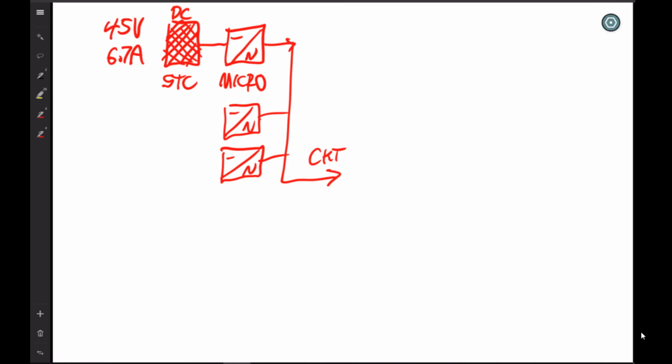I believe I have 13 modules on my roof, and I use microinverters at my house. I didn't design it, so I'm sure they're microinverters, but I'm not sure what, well, they're in phase. So it's probably 1-for-1. And I believe that microinverters are typically about 2 amps output. I might be making an assumption there, but if I have 13, that means there's 2 circuits that tie into the panel. They could also be produced at 240 volt, and might be 1 circuit then at that point.